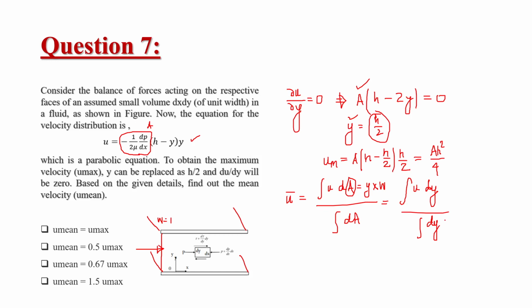Now it is given that this is a stationary parallel plate. That means the velocity of the wall is equal to 0. So the velocity near the plate, that is u, which is equal to u wall, will also be equal to 0. So the velocity near the plate will be equal to 0. Okay, now let's move on to the next question.